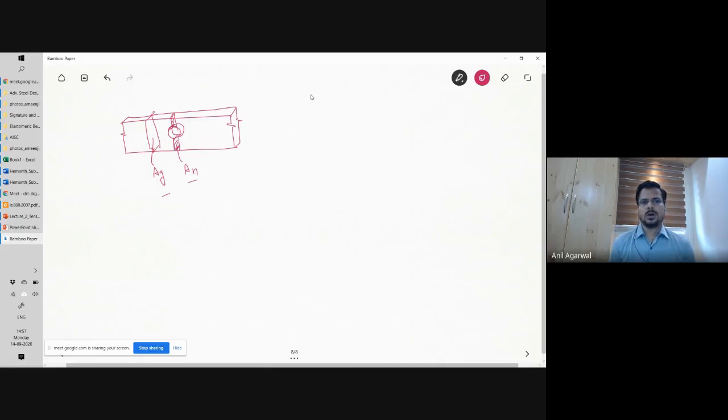So I would have said that AG multiplied by Fy would be the limit state if there are no holes in this plate. But if this plate has any hole anywhere along the length, then the available strength will be only A net multiplied by Fy. But that's not what the code says. The code says we need to do Ag multiplied by Fy.